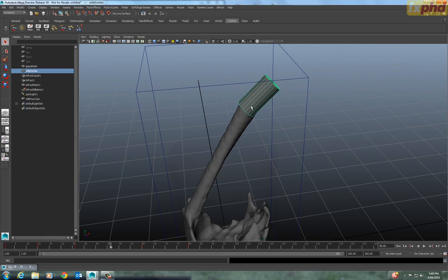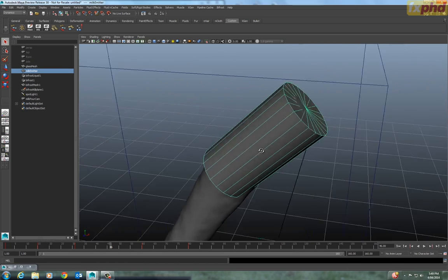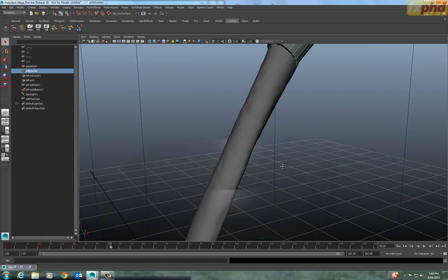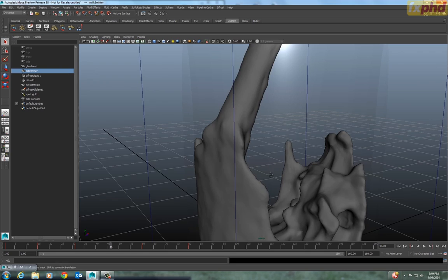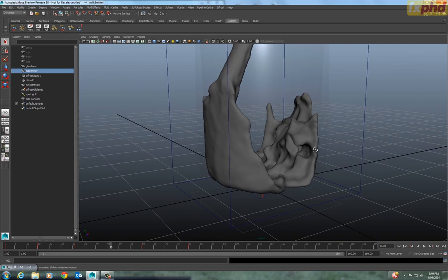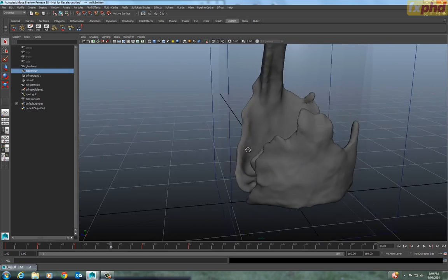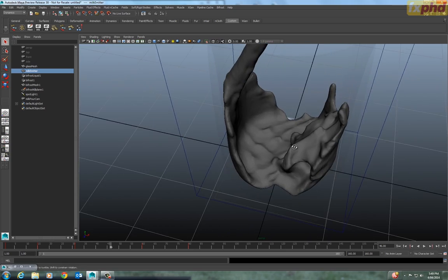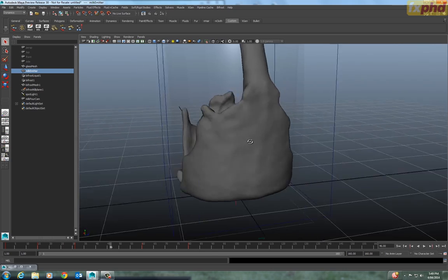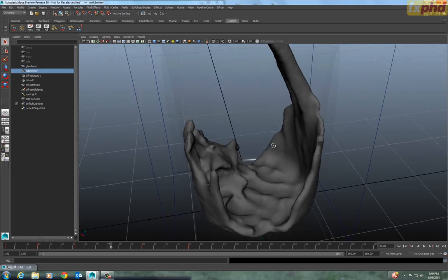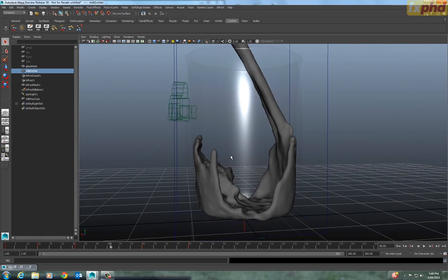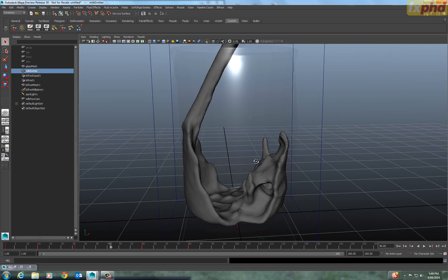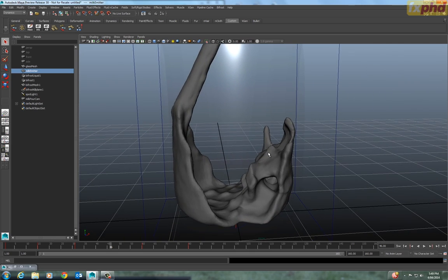Millions and millions of particles are coming out of that, pouring into that collision object, running the scientific fluid simulation algorithms to create the lifelike movement. And then a separate process is being run to triangulate a geometry around the particle simulation to give it a solid milk-like surface that can be rendered with the shader.